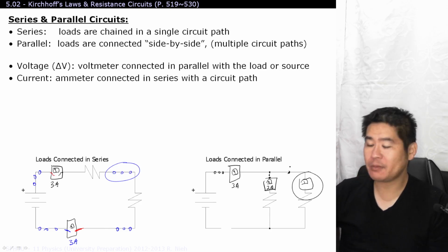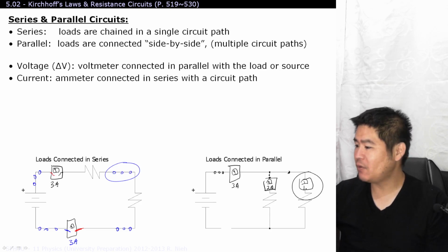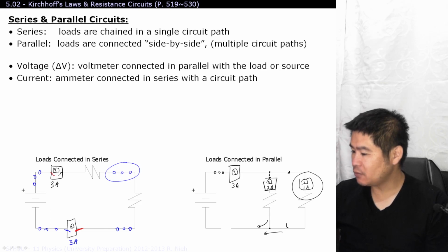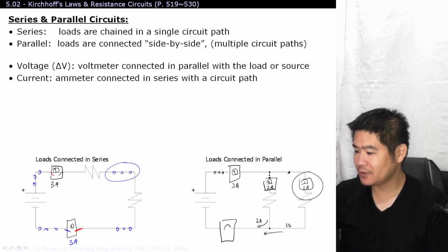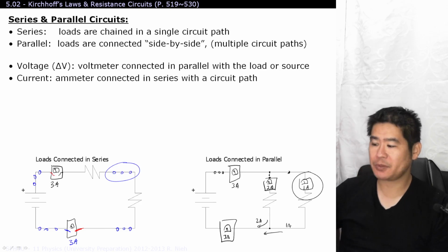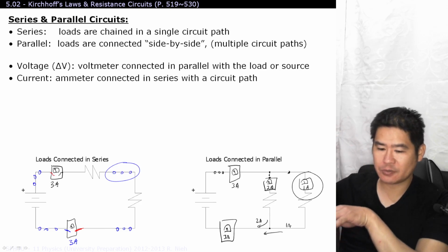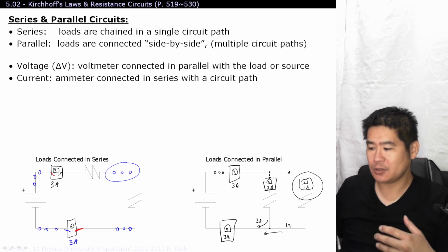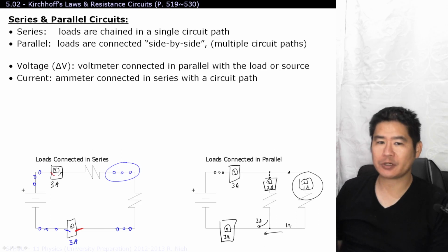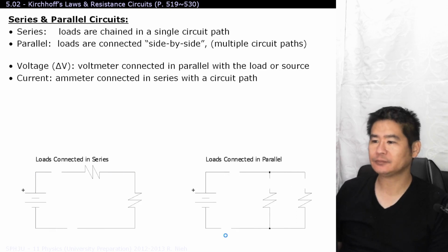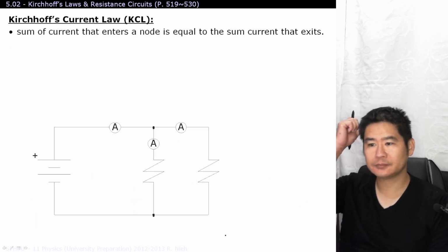Well then, logically, how many amperes of current flow through here? Excellent. 1 ampere of current. And you can see that they will rejoin again. The 1 ampere will rejoin with the 2 ampere, giving you a total of, excellent, 3 amperes again. You can't have electrons disappear in a circuit. So if you start off with 3, they may split off into 2 separate branches of the circuit, but when they return back, you should still expect to see 3 amperes of current per second.